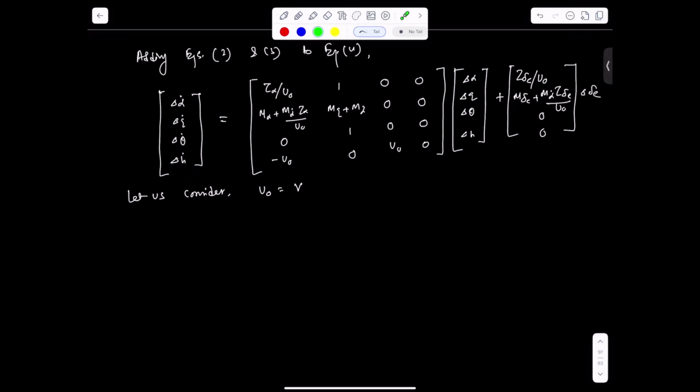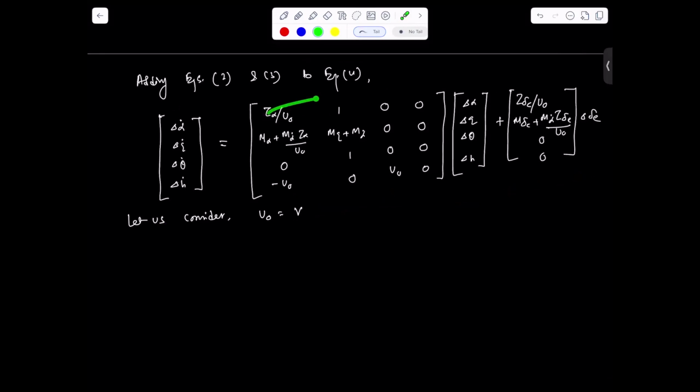So let us first define the problem. This is basically the natural dynamics of the system, in the linear domain of course, and these are the parameters that vary from aircraft to aircraft. For a particular flight regime, we can get these parameters from wind tunnel testing. These are basically stability derivatives, moment and force stability derivatives, and this varies from aircraft to aircraft. Now, example.